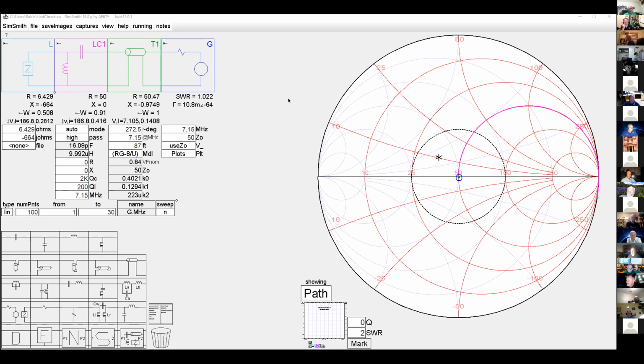But what I wanted to tell you, I don't know if you're familiar with, there's a couple of programs that have been around for a long time. TL Details. Dan McGuire, AC6LA, did a very similar program to this, although it's not graphical with the Smith chart, but all these calculations and all the characteristics of the coaxes are in there. And it's another free program. The graphics here help you understand, oh, I see why that's working. But after a while, you may not need the graphics, because in your head, every half wavelength things start to repeat, and a quarter wavelength is an inversion and things like that.